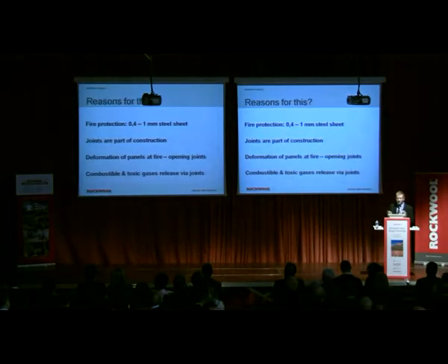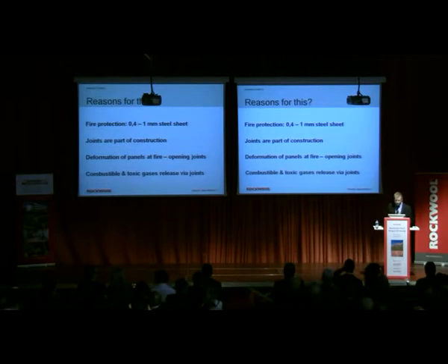And what are the reasons for this kind of performance behavior of sandwich panels? The first reason is that the fire protection is only a very thin steel sheet, which does not prevent heat from coming through to the insulation. Now we can see as thin as 0.4 millimeters thin steel sheet here, but it's not integral. It has joints, and these joints are never perfectly tight. So they deform, and combustible gases can come out from these joints.